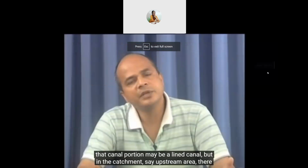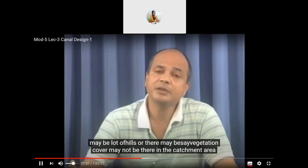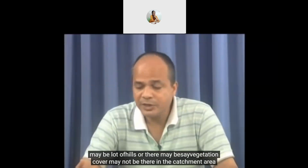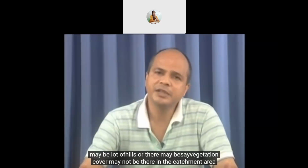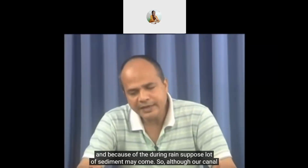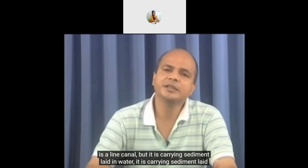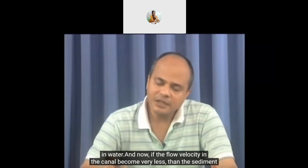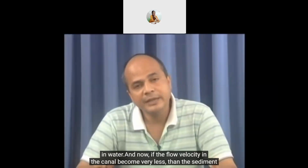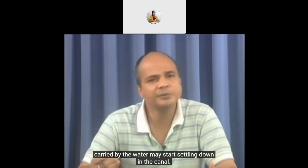Canal portion may be a lined canal. But in the catchment, say the upstream area, there may be a lot of hills, or vegetation cover may not be there in the catchment area, and because of that, during rain, a lot of sediment may come. So although our canal is a lined canal, it is carrying sediment-laden water. And now if the flow velocity in the canal becomes very low, then the sediment carried by the water may start settling down in the canal.